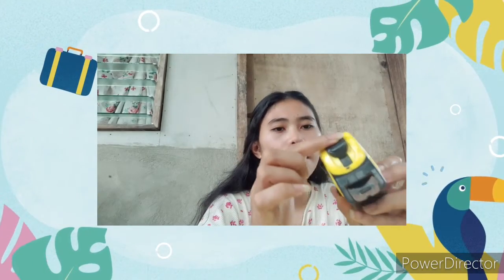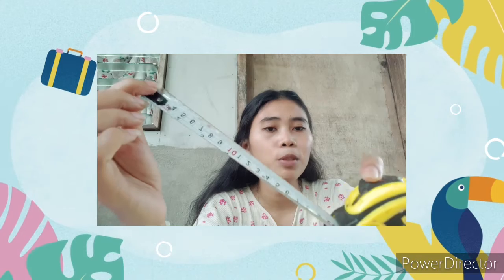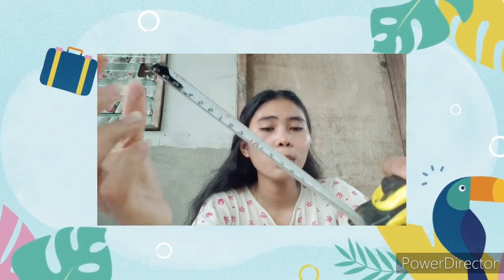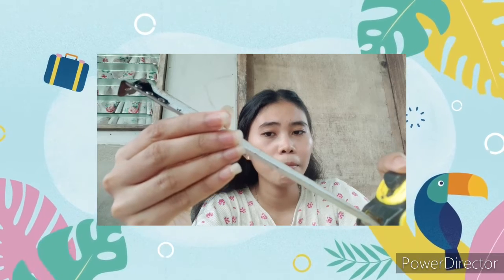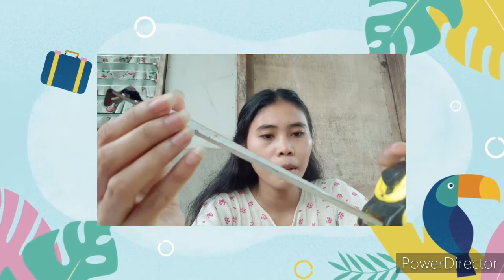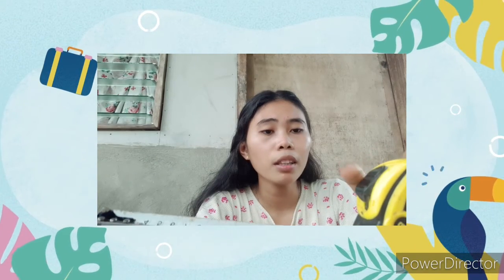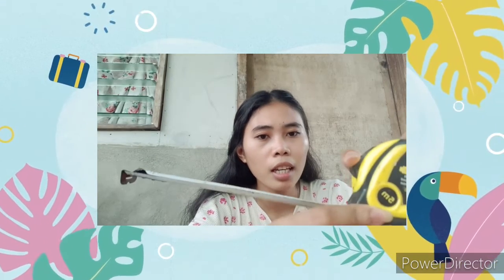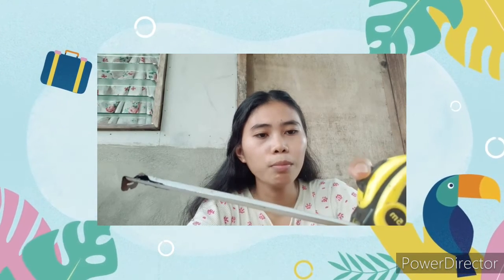This is the thumb block, the case of the tape measure. These are the hooks and the blade tape. The primary purpose of the thumb block here: if I push down the button, it will lock or prevent the movement of the blade tape. So it will prevent the blade tape from going back to its case. And if I push the button upwards, it will enable the blade tape to move back to its case.